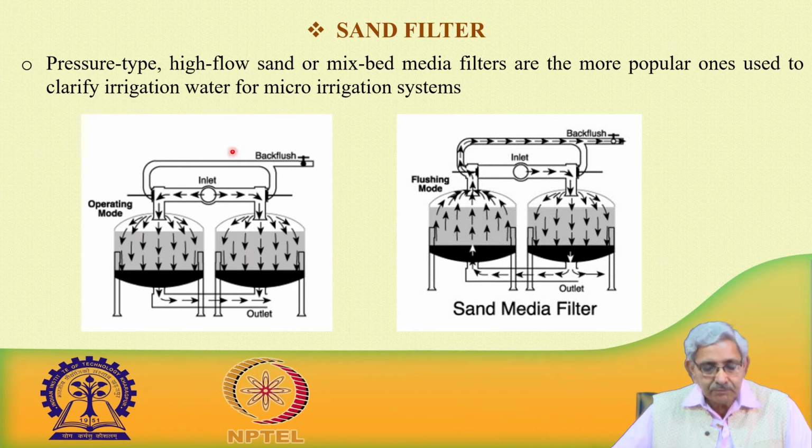in that case, the double cylinder sand filters are used. Now, this is in filtration mode, means when the filters are working, this is in filtration mode. Now, when we have to see that the water should continue to flow in the system, in that case you may find that the pressure across the filter decreases because of the clogging of the filter. So, back washing is important. So, back flushing is done.